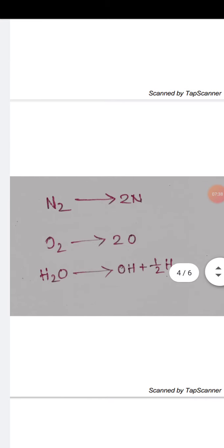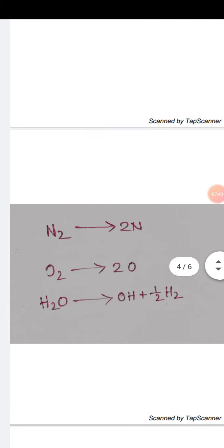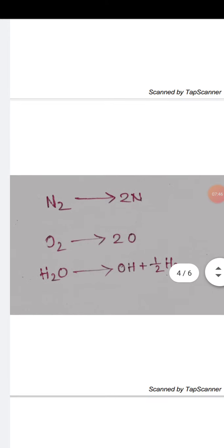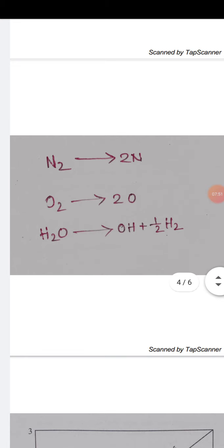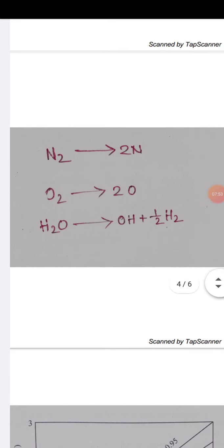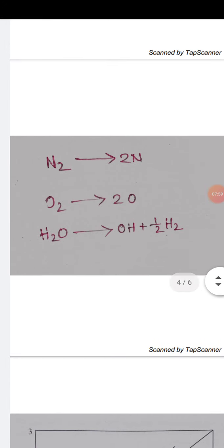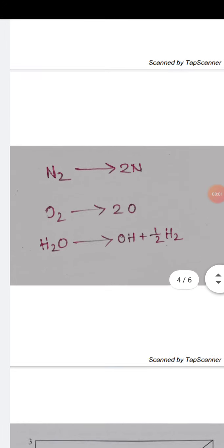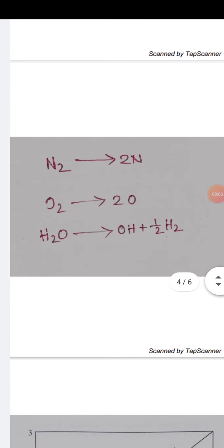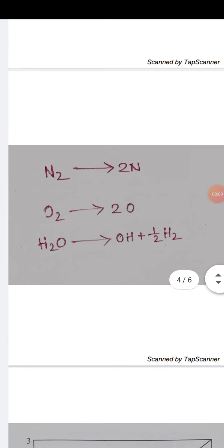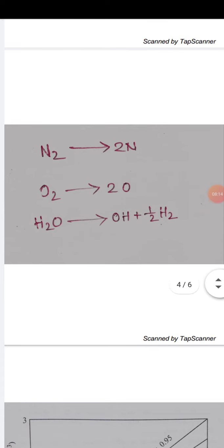It is mainly a temperature-oriented reaction, meaning that if the temperature varies, then the reaction rate also varies accordingly. A significant amount of monoatomic nitrogen is generated in the temperature range of 2500 to 3000 Kelvin, and that can exist in an engine.